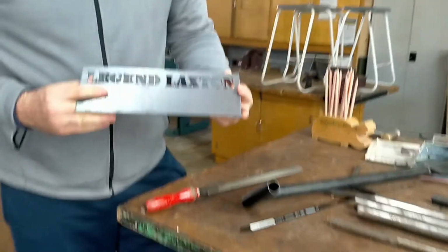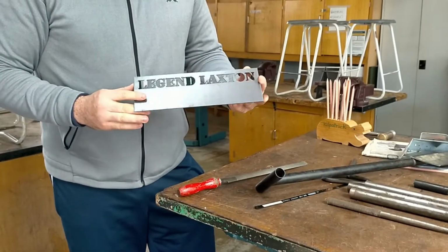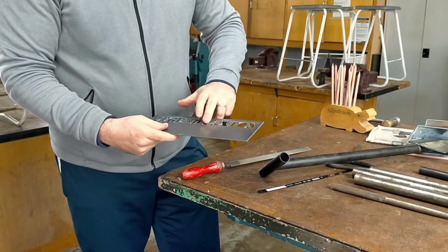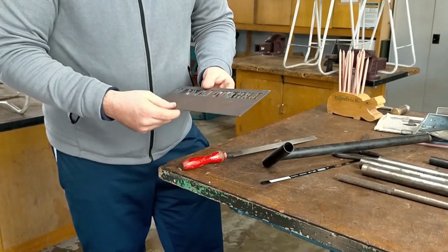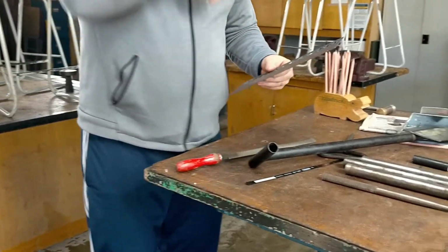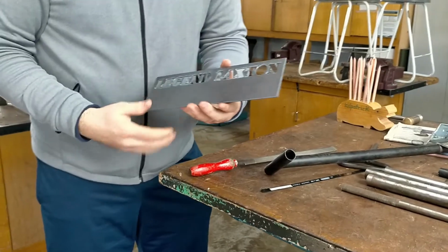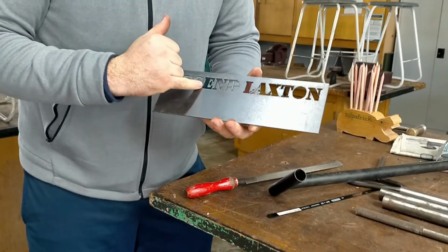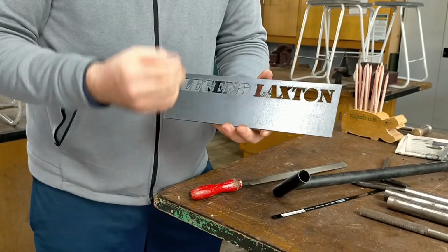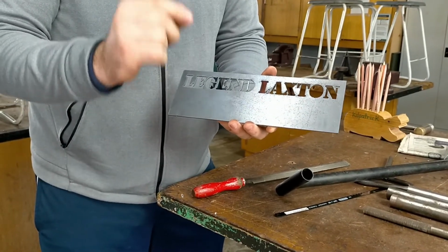So you can see here that I've got my nameplate out, is what I was calling it. It does have a little bit of slag left on both the front face and the back face, which I'm just going to use a file to get out. In terms of drawing this up, I now know that the CNC plasma cutter has a 3mm kerf width, which is how much distance the cutter actually takes up.